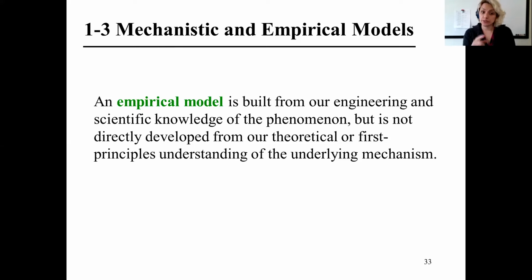So what would we do with the empirical model? We are going to get the data, and I said that we have 3 types of data, right? After we get the data, we are going to make our model for it. We are going to relate the variables in our model. For example, in the distillation column example, we are going to find out the relation between the reflux ratio, reboiler temperature, and condensate temperature, right? So this is going to be my empirical model because I found this. If you find your model from the data points that you have, that's going to be your empirical model.